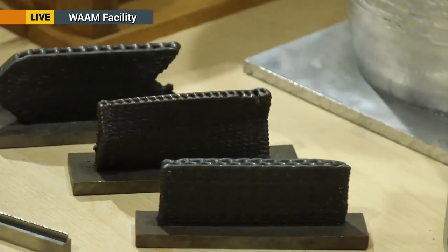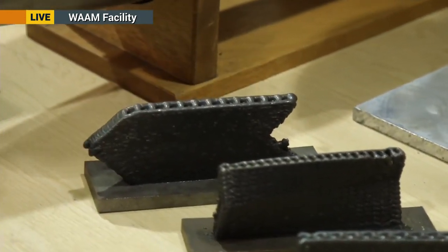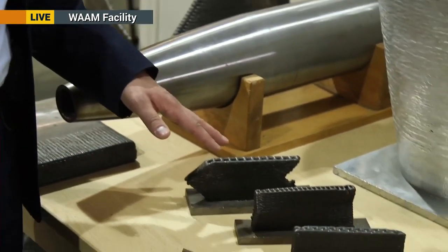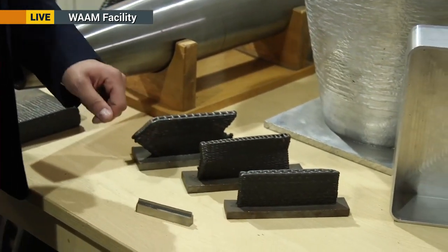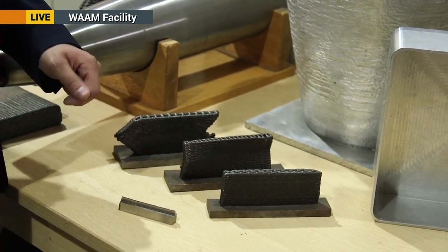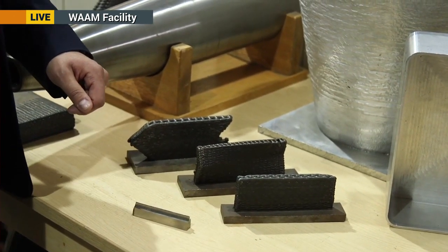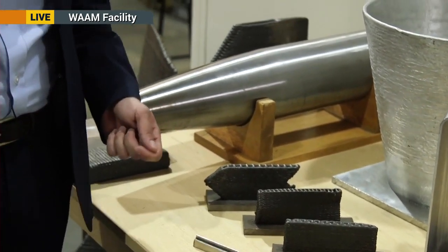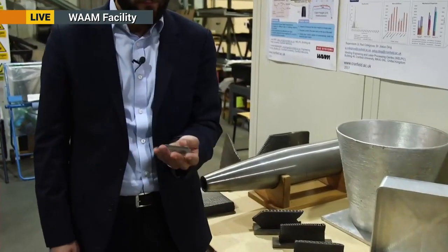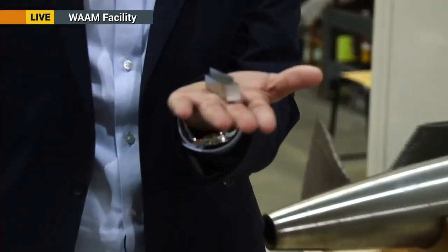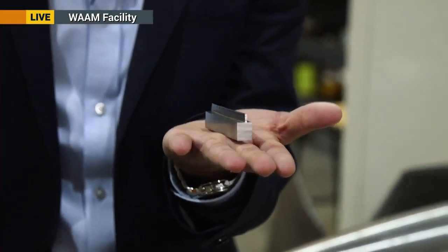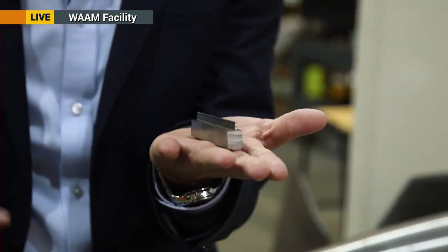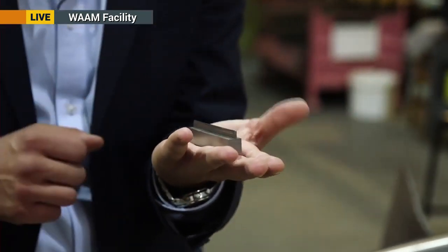And then finally, in terms of going forward, looking at how we can expand the geometrical capability of this process, we've been working very recently on dies for automotive application. This in particular is for the press forming of the A, B, and C pillar of your car chassis, as well as using other heat sources, like in this case, where we can deposit using a laser instead of an arc, and we can deposit much thinner structures which crucially do not require any finish machining after they've been deposited.